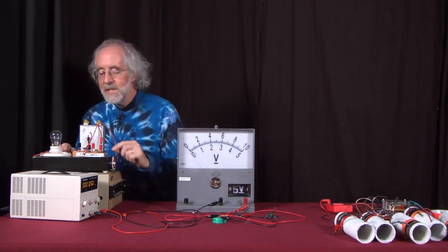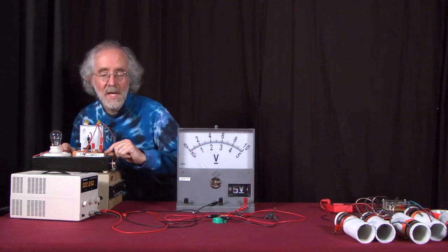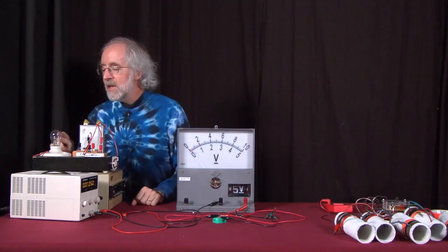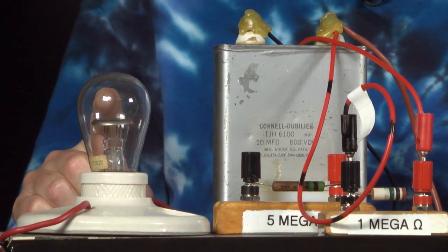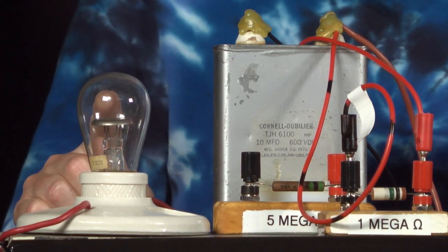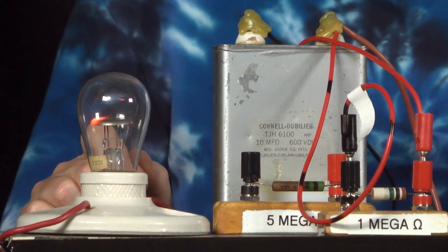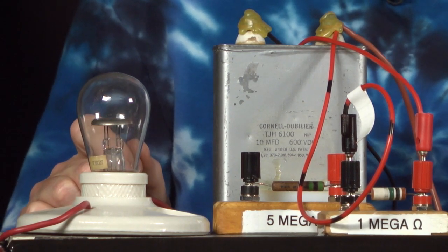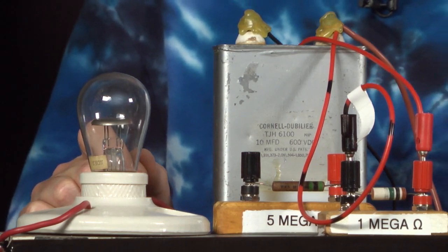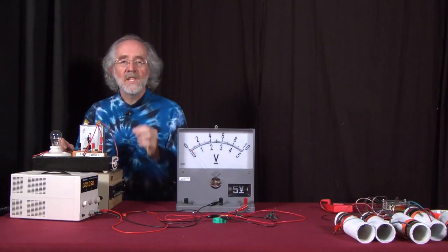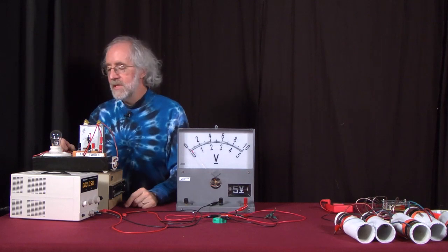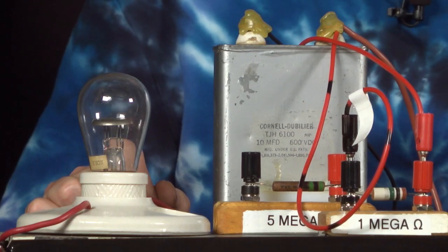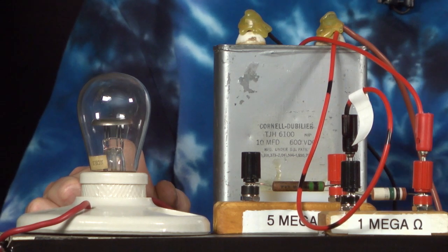Now I'm going to take this 1 mega ohm resistor in this circuit and replace it by a 5 mega ohm resistor in the circuit. Now look at the flash rate of this circuit. And that is a measure of the time constant of the circuit. Bigger time constant, there's going to be a bigger time between flashes because it will take longer to charge. I'm going to take this 1 mega ohm resistor and switch it for a 5 mega ohm resistor. How will that change the flash rate of the neon light bulb? We'll give you some choices.